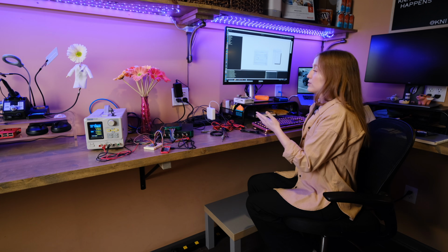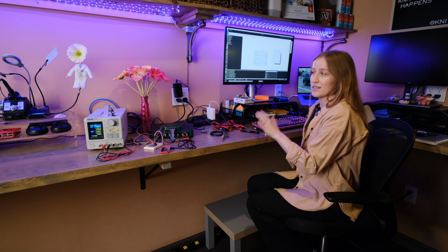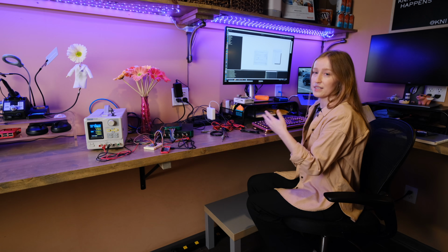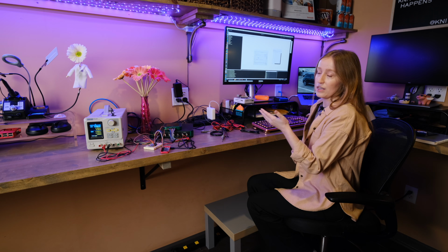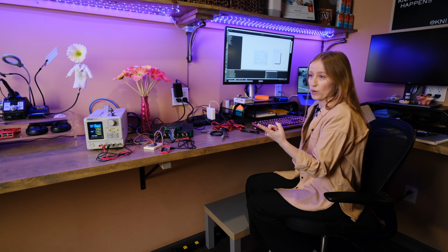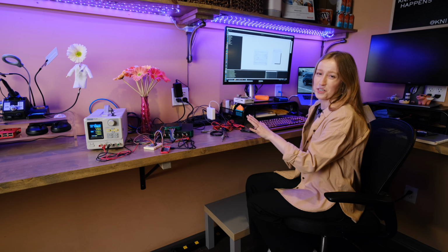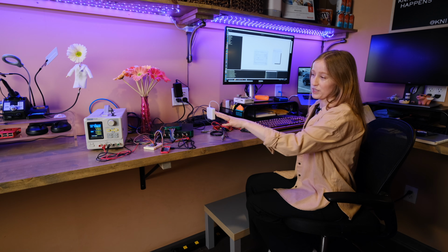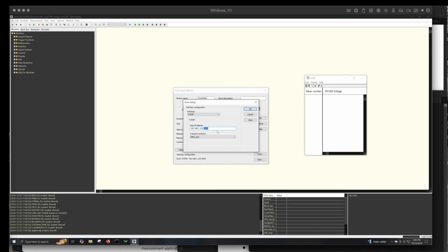I want to make note that this is not a standard thing that's common to every single device. Like I said, it just needs to be an open port that's not commonly used for other things like external traffic, port 80, or SSH, port 22. So you always make sure to check the datasheet or user guide of your particular instrument. And then under transport protocol, I just choose other because it's none of these other things. It's just a plain old socket.